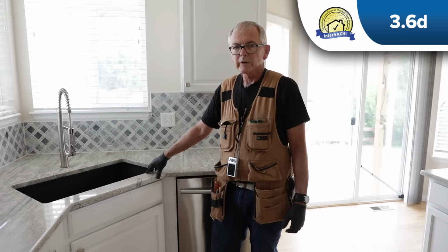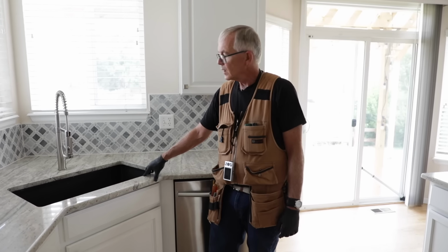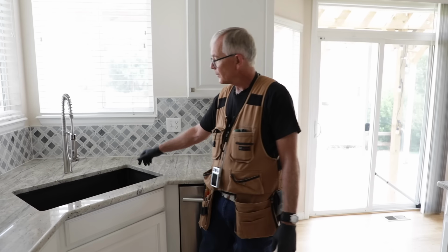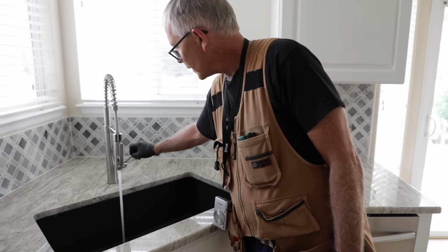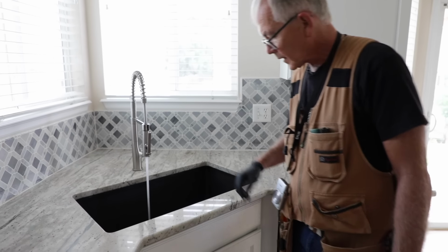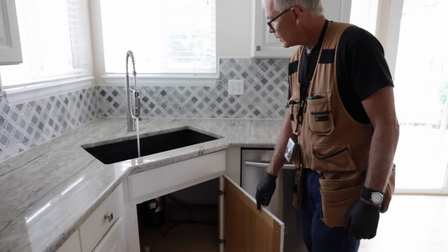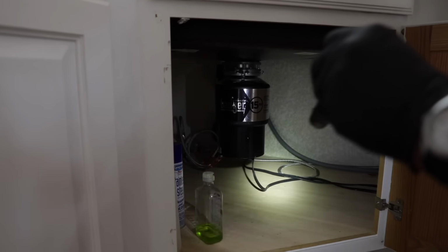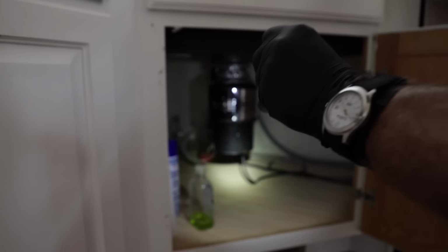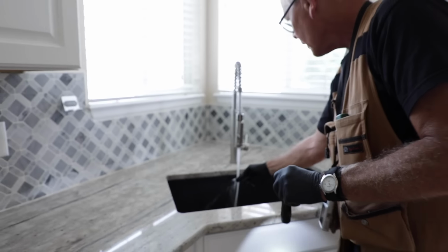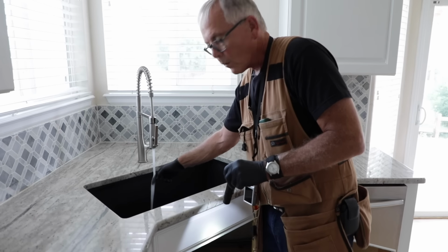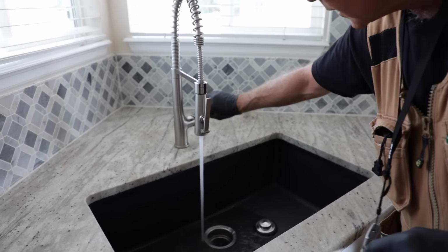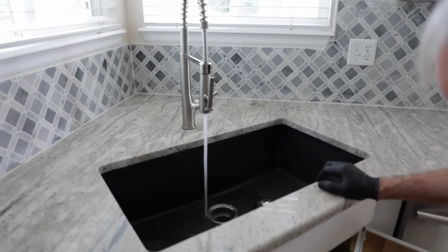Okay, now we're going to be doing the interior water supply, which includes all of the interior fixtures and faucets, and we're going to do that by running some water. We're in the kitchen right now. We're going to start with running some water. I'm going to take a look down here and make sure that we don't have any obvious leaks. Running some water. Not seeing anything so far. The next thing you want to do is just verify you got hot water. So right now we're in hot, and I have verified that it's hot. So I'm going to move to the cold and go back down here again.